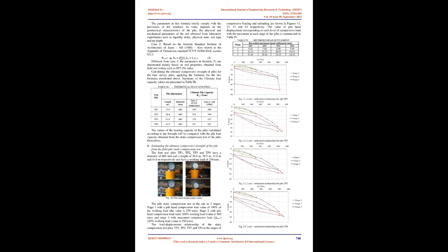Another method that can determine the ultimate bearing capacity of piles was proposed by Chin, based on the research results of Chin-Kondner [7], and allows the extrapolation of the failure load in static load tests. The method consists of dividing each respective load applied by the settlement and putting it on the y-axis. In turn, the x-axis shows the settlements obtained during the static load test. The load limit is given by the inverse of the slope formed by the points plotted on the graph.